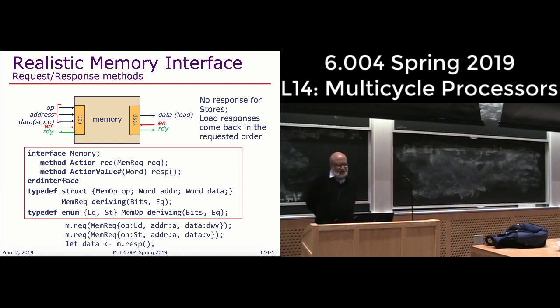So the important thing to understand here is the structure of a request. Memory has only one port, so all the reads and writes go through the same port. The thing you feed to it has to have an opcode in it, which will be either load or store. Any time it's a memory operation, you have to have an address with it.